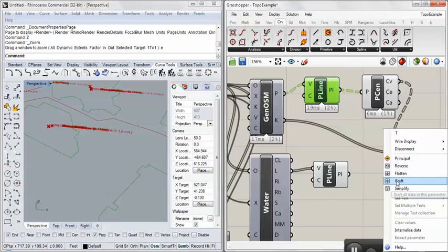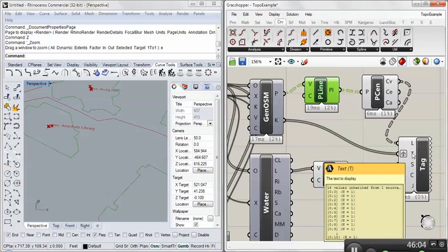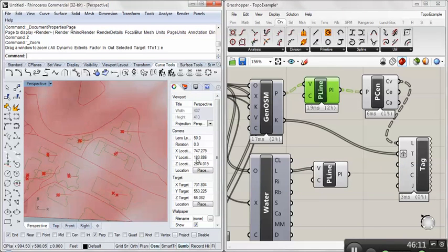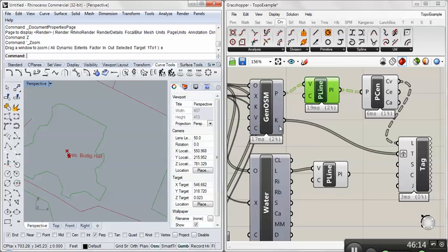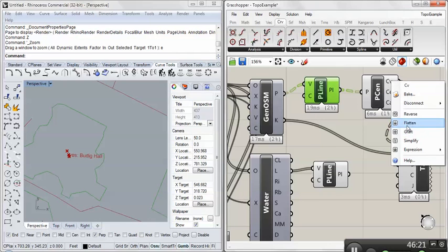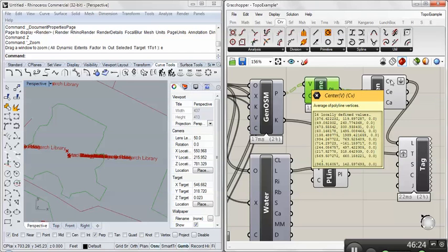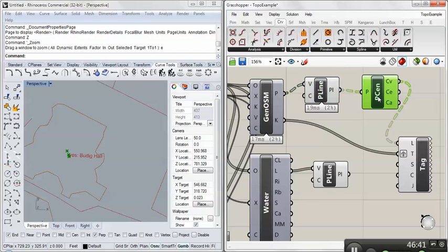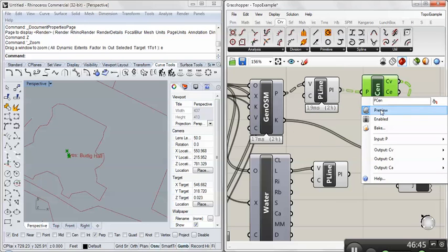And the term for that is grafting. So if I do this, right click on that and I graft it, it makes a data set for each. So graft and flatten are the opposite of each other. If you wanted to look at just the flat data here, flattening it, now I have just points. So I'm going to go ahead and undo that, but that's the back and forth with data, to either flatten it or graft it. That means make it structured or make it just a big list of items. So we don't care about these points anymore. I'm going to hide them, preview off.